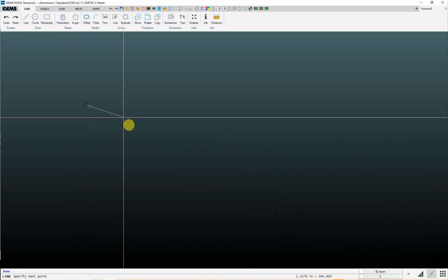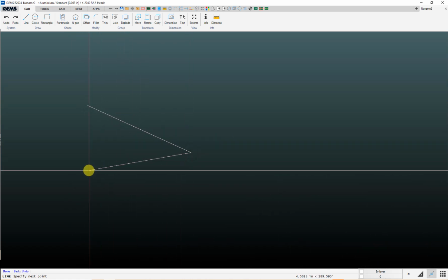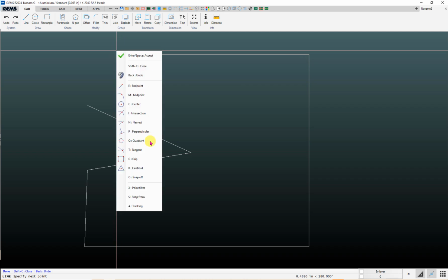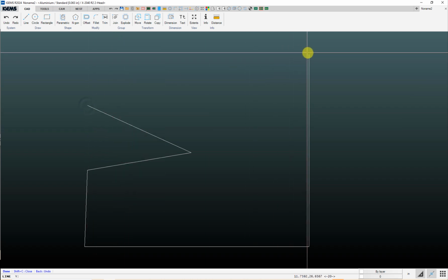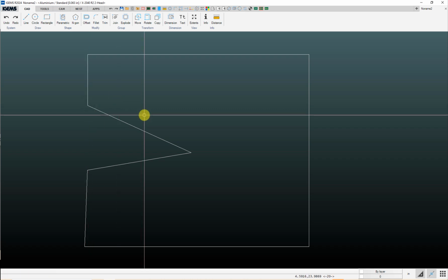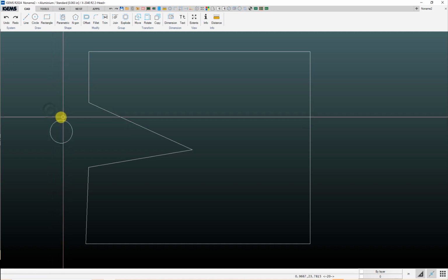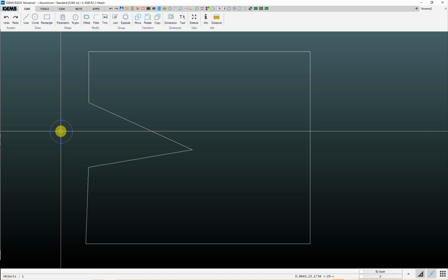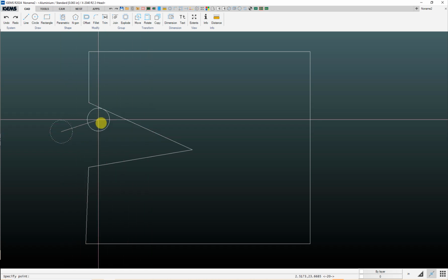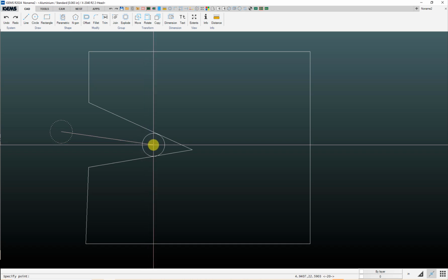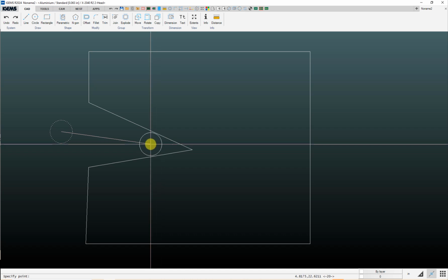It's not drawn to scale, but if you had something like this, and let's say this circle represented your 40 thousandths stream width, with the geometry optimization turned on, IGEMS is going to look at that maximum tool diameter and determine how far down into a geometry like this that the stream can go before it starts digging into your part.